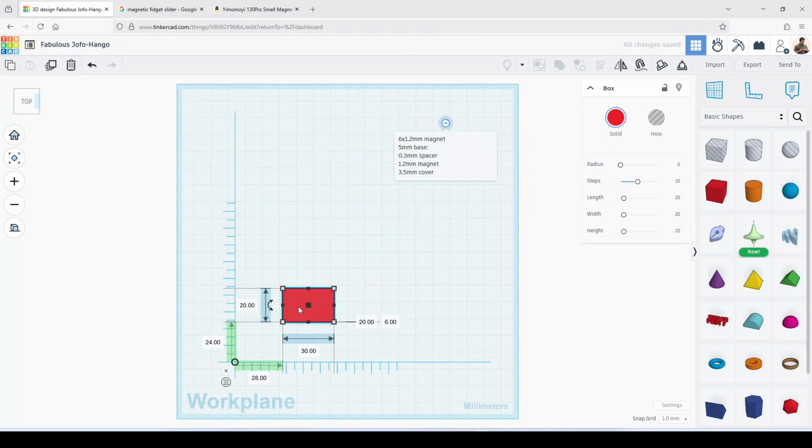All right. What about the height? So a very similar concept over here. Again, we use 6 as our base unit. So we have 4 rows of the magnets, and then we will have the space between them. So we have 4 plus 3, so we have 7, and then the margin will give us another 2 sets of 6, so we have a total of 9 sixes. So that's 54 millimeters. So we type 54 over here, and that's how our base is going to look to start with.